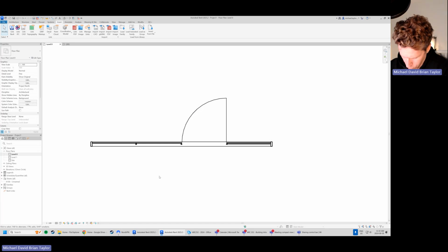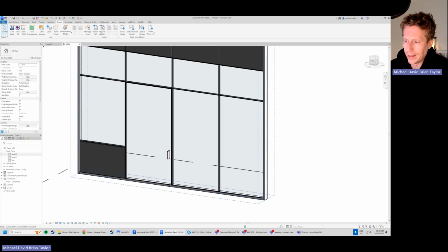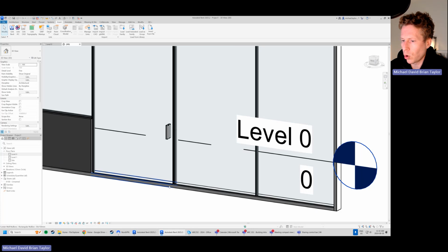That is the doors. So one thing, just lastly, you might notice that in our curtain wall family here, you wouldn't normally have a mullion below a door. So if you're ever entering a building or something like this, you don't typically have that rail, what we call the curtain wall rail, extend below a door, right? So it's usually just a transition piece or something like this.